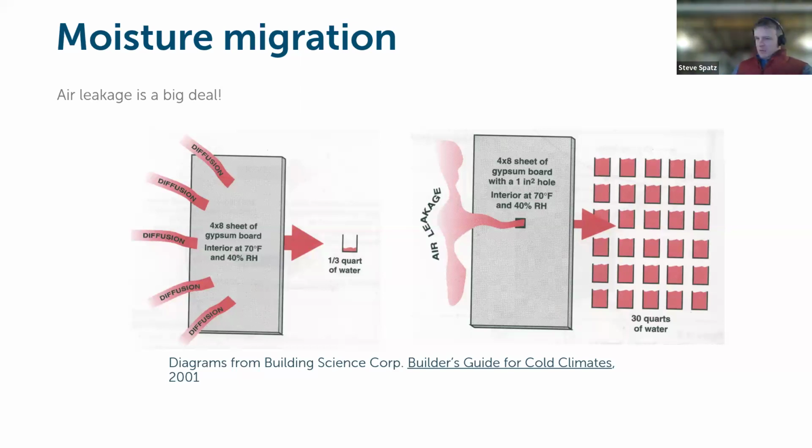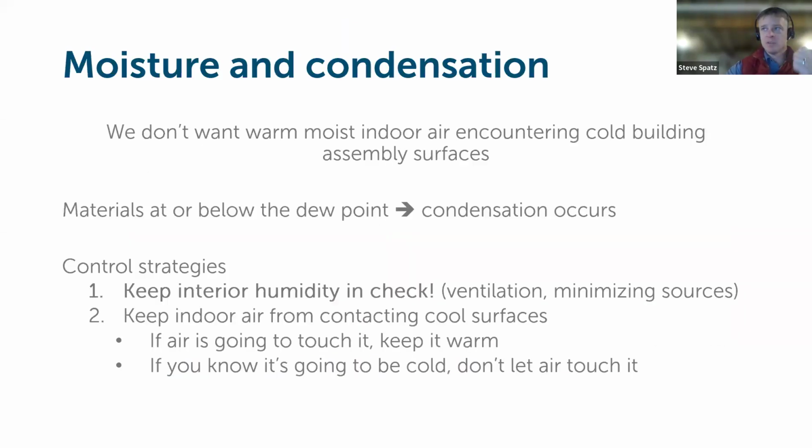So that whole idea, like I showed with the balloon, pressure differential, you start poking holes into it, the amount of moisture vapor transport that can occur through these small gaps may seem inconsequential in their own distinct consideration, but when you start to magnify them across the scale of an entire wall assembly or roof assembly or an entire building, you can get to the point where you get so much transport of moisture into an assembly that you start to get damage, which is what was asked about in that early slide: how does this damage happen? Why are we looking at that picture of that rotted OSB? This is why. This is what can happen. So we have to keep these things in check.